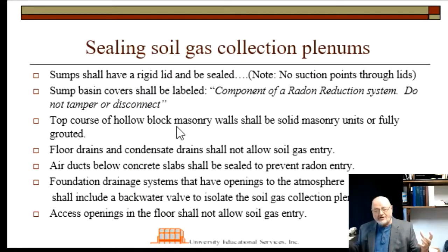And the radon can come through the soil and through any spaces in the block wall, including the block walls themselves, and get into the cores of the block walls, the void spaces within the blocks. And then it can drift up, and if the top of the block wall is not capped and sealed, then that radon gas can, of course, just get right into the basement.